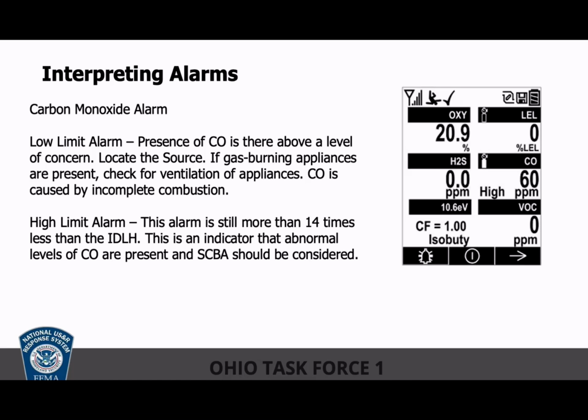For CO, looking at this alarm display, we've got 60 parts per million. So you're going to see 35 parts per million in our meters and our MultiRAEs as our low, 70 as our high.